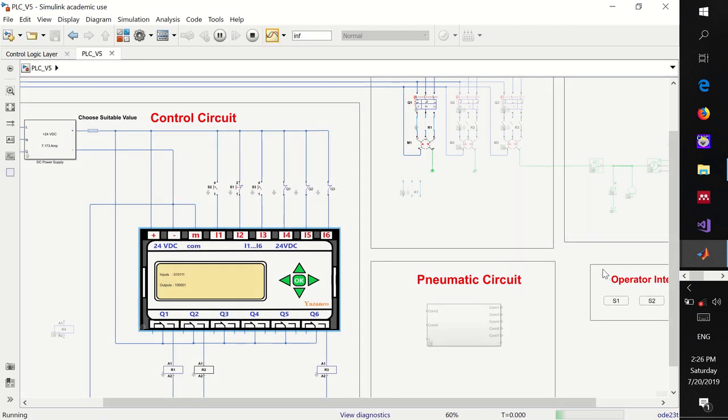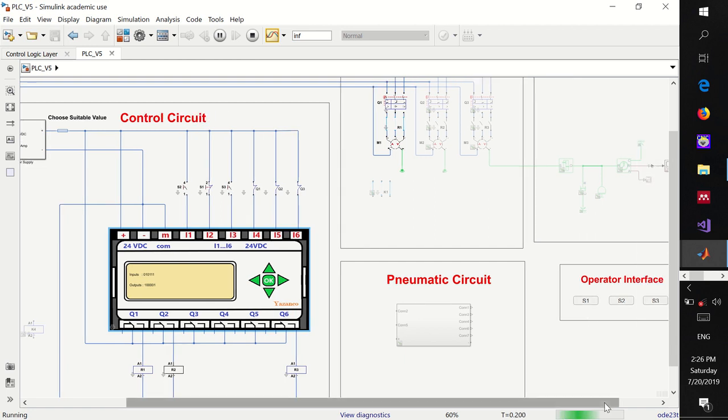So this is the associated user interface. Here, once we hit S1, you observe now how the states are updating and the corresponding logic is taking place. So let's push S2. Now we are deactivating the first output, and as a result, the contacts are disengaged and the motor will stop, as you can see in this region.